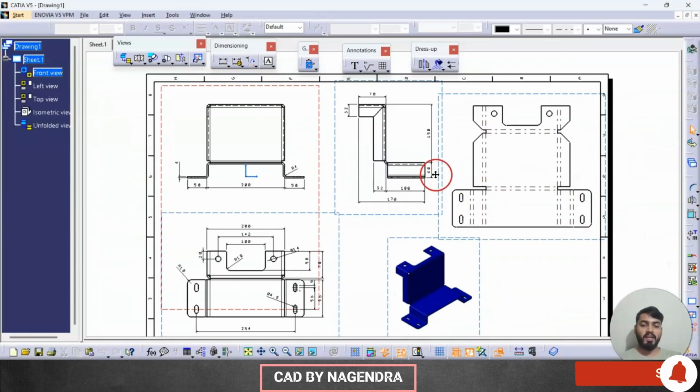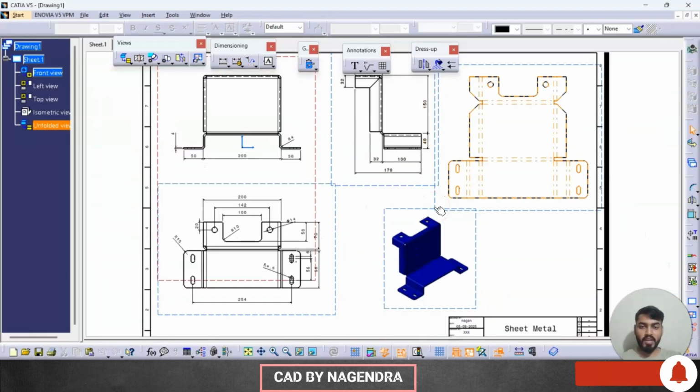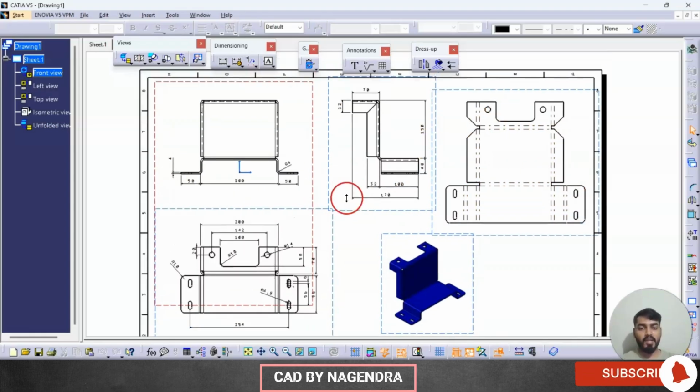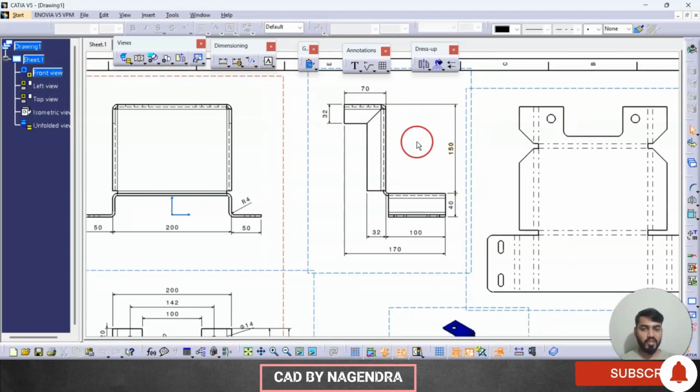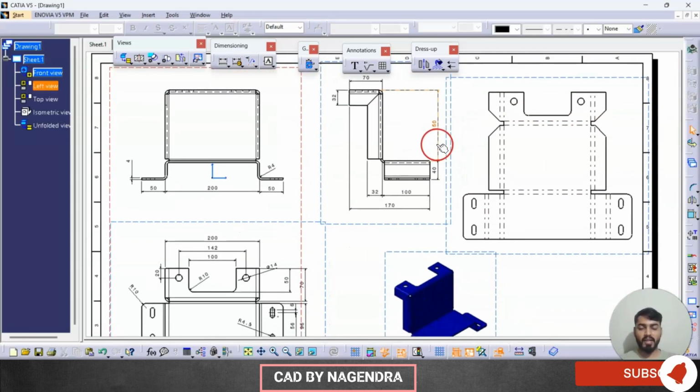So sheet metal bending is very complex. If you are going to create part designs, if you make a step inside or upside, you will get a huge difference with the dimensioning. So while creating, we need to make sure how much dimension we wanted and whether the material should be inside or outside, that we need to check. If by mistake we have made any mistakes, again we will come to know in the drawing. So here we can change by observing the dimensions. So I hope you understood the sheet metal design, how to create it in CATIA.